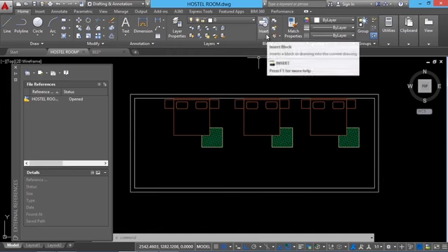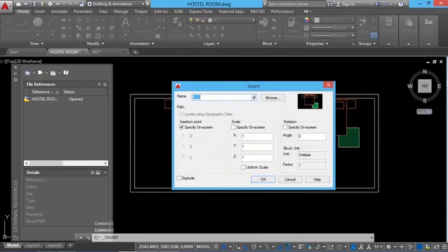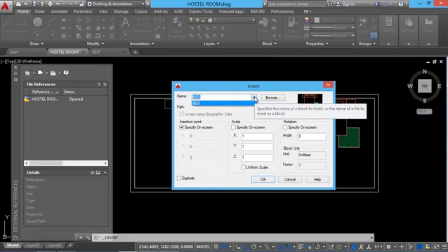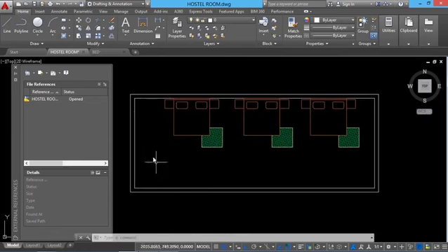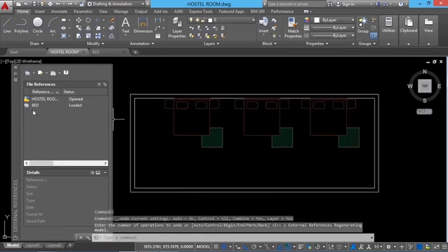Just click on the insert command and you will see the bed as a definition here, because this area indicates the number of block definitions you have in your drawing. Now I'll undo this change. Now it is back to Xref. It is no longer a block definition.